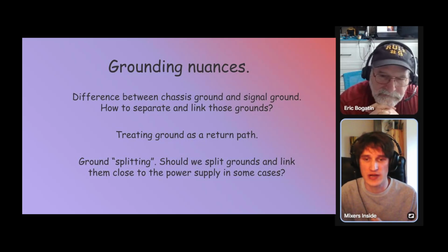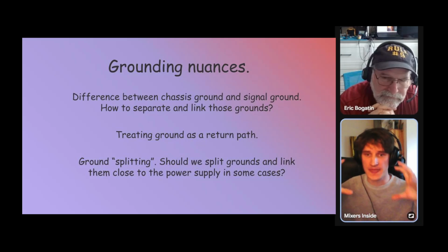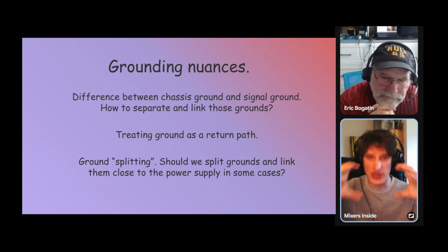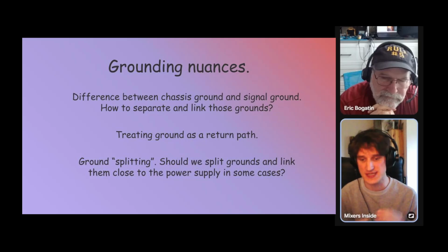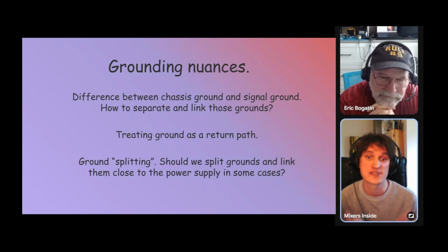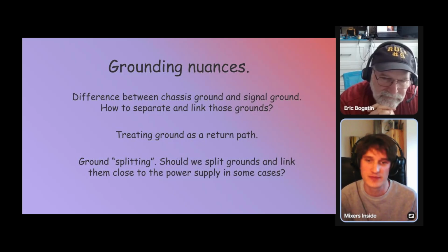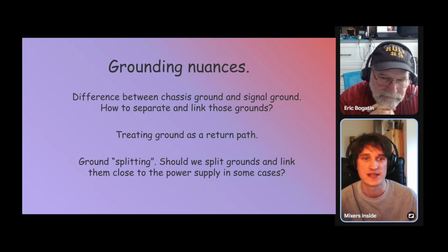We see that people are separating the chassis ground, so the ground that is connected directly to the metal chassis, and signal ground, so the ground that is connecting our reference plane to the reference plane, or maybe not plane but some reference to other signals.